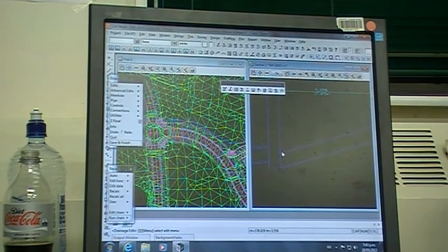You might find the odd time, in fact, here's one, the outlet, the pipe coming in, is too low. It's only because it's just its first default. Once we run the network editor and tell it to regrade, it'll fix all those things. It's just got in there and stuck to our defaults.